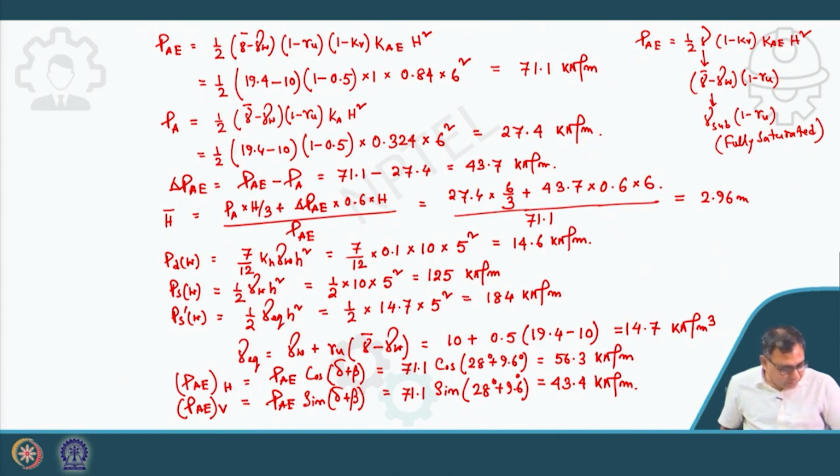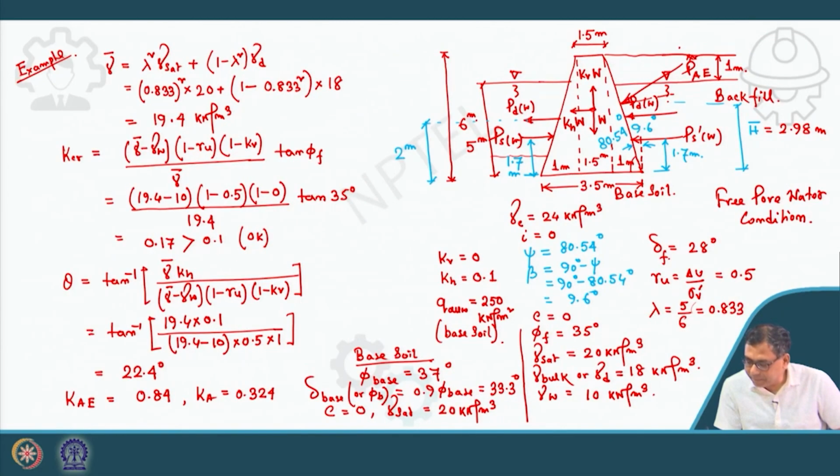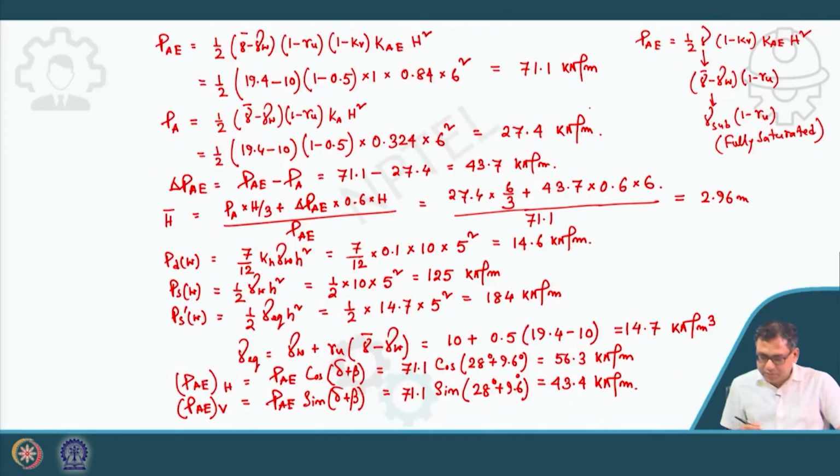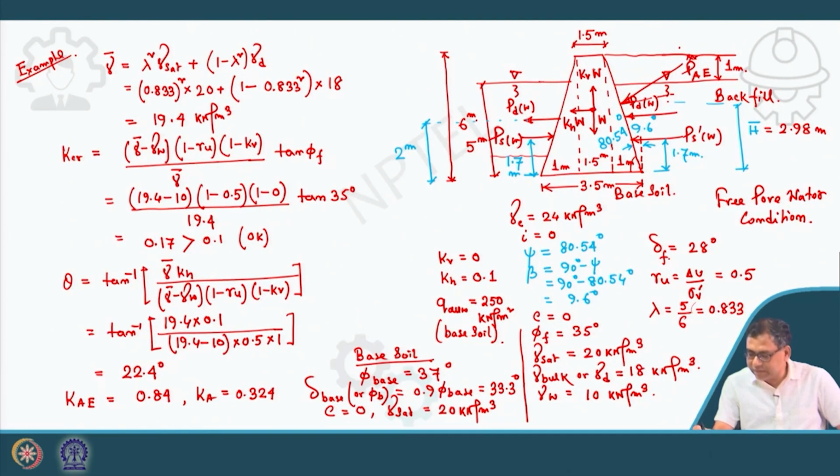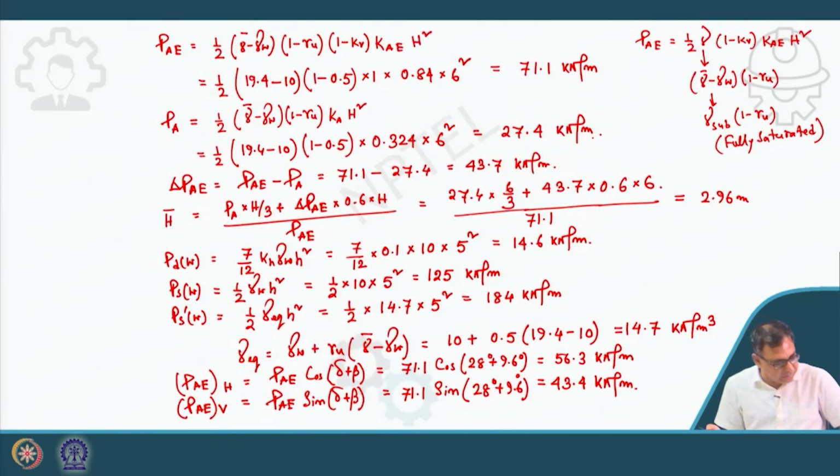Okay. So, before the sliding part, I have to calculate this W1 centroid position. Vertically it will act at half, but horizontally I have to calculate it first. So for that I am calculating the W. What is the W? I am taking these two triangles and this rectangle, divided into two triangles and a rectangle, the total W.